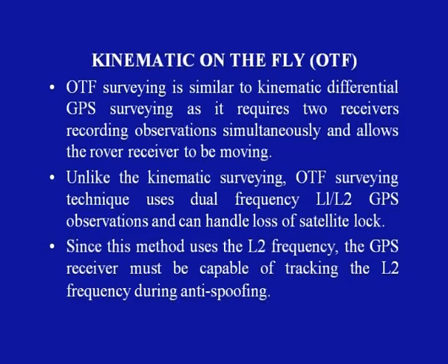Now we focus on the next method, and that is kinematic on the fly, or in short OTF. OTF survey is similar to kinematic differential GPS surveying, as it requires two receivers recording observations simultaneously and allows the rover receiver to be moving. Unlike kinematic surveying, OTF surveying techniques use dual frequency L1, L2 GPS observations and can handle loss of lock. Since this method uses L2 frequency, the GPS receiver must be capable of tracking the L2 frequency during anti-spoofing.